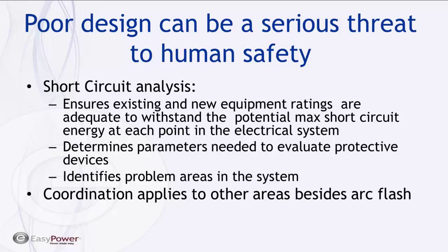Obviously, a poor design could be a serious threat to human safety, and the primary purpose of short-circuit analysis is to ensure that we understand what the worst-case arcing currents will be at any point in the system and identify problem areas that need to have attention in terms of mitigating the safety factor.